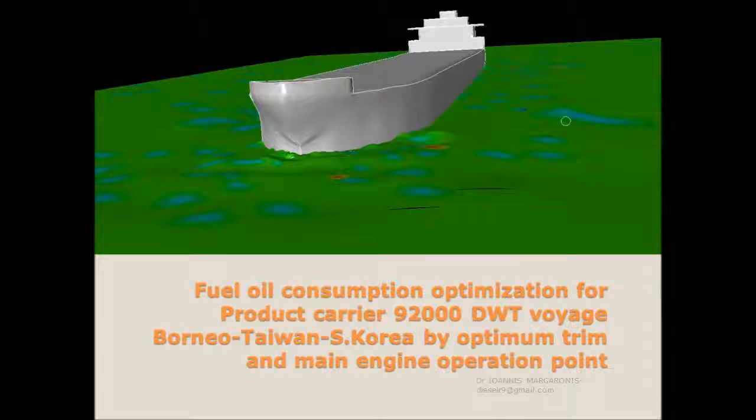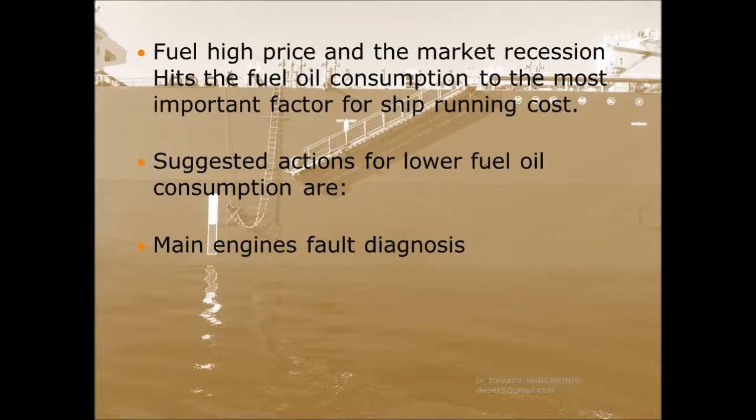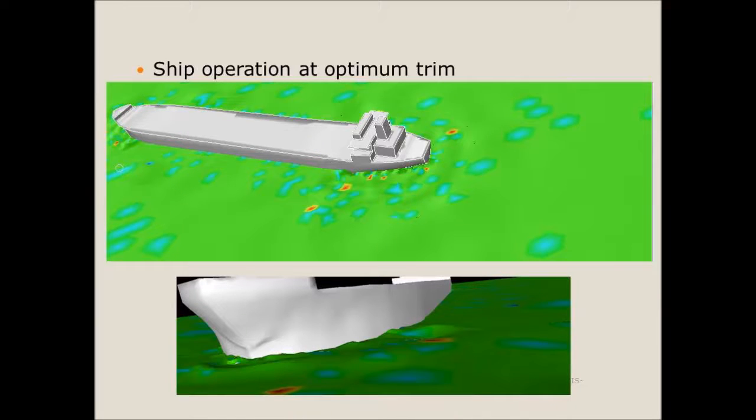Fuel oil consumption optimization for a product carrier, 92,000 DWT, voyage Borneo-Taiwan-South Korea, by optimum trim and main engine operation point. The high fuel price and the market recession make fuel oil consumption the most important factor in ship running cost. Suggested actions for lower fuel oil consumption are: main engine fault diagnosis, ship operation at optimum trim,